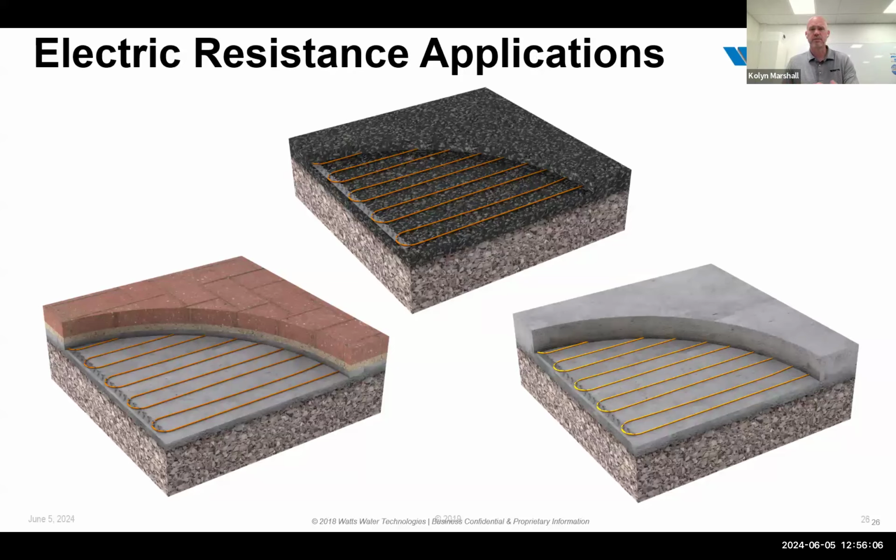Asphalt can be used. A lot of times asphalt is recommended or used as a floor covering or a driveway surface covering because of cost. It costs less than sand and brick pavers, and it costs less than concrete. You can use it. Keep in mind the following, though. Asphalt has half the conductivity of concrete. Concrete has a conductivity of 0.81. Asphalt has a conductivity of 0.42. What does that mean?